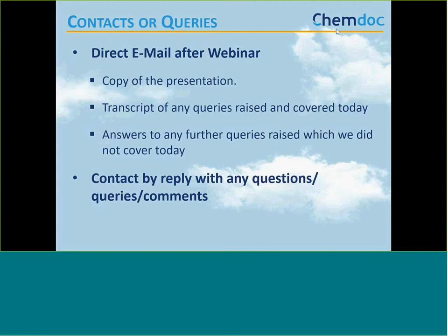In an extreme circumstance, if there's no other way to get that product and it's absolutely critical to your process, then you can do your best to write a COSHH assessment without the safety data sheet. But really, we would recommend, if you cannot source the safety data sheet for the product, it should not be on your site, and you should look to source that product from a supplier that can supply you with a safety data sheet.